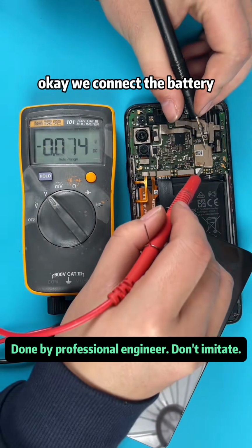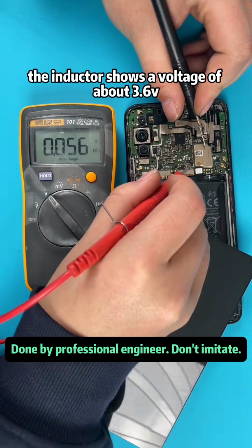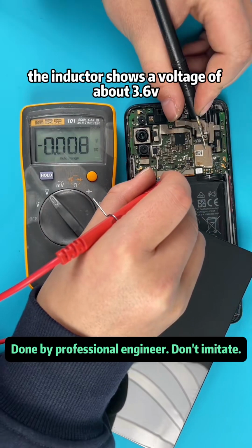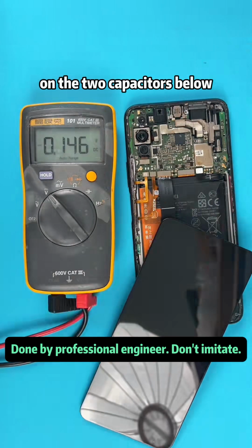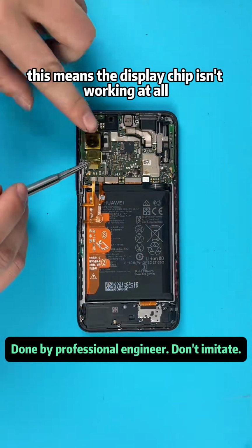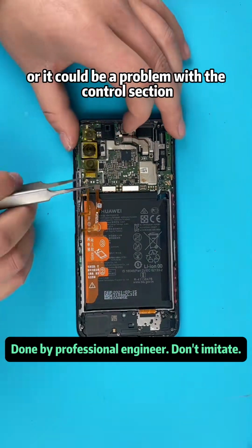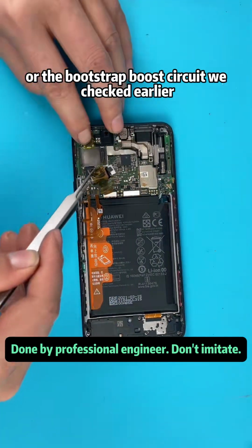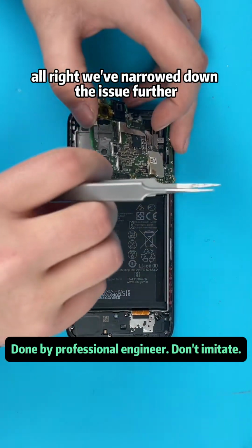Okay, we connect the battery. After powering on, we immediately test the voltage. The inductor shows a voltage of about 3.6V, but we don't see plus or minus 5.5V on the two capacitors below. This means the display chip isn't working at all. This could be due to a faulty display chip, or it could be a problem with the control section or the bootstrap boost circuit we checked earlier. Alright, we've narrowed down the issue further.